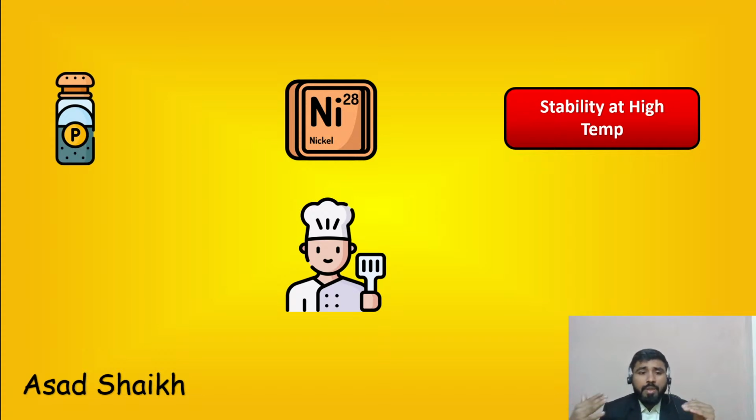If your fluid is okay, if the piping material is carbon steel, and you don't need especially high temperatures, corrosion is not going to be there, then I prefer going with the carbon steel body. You will save a lot of cost. So based on that, you can select your application.